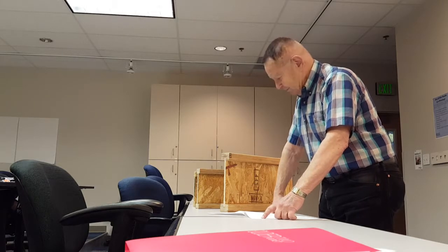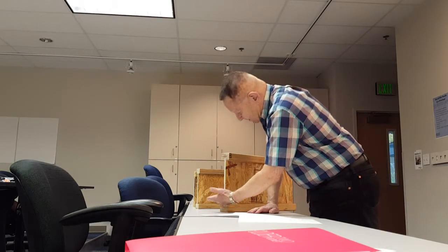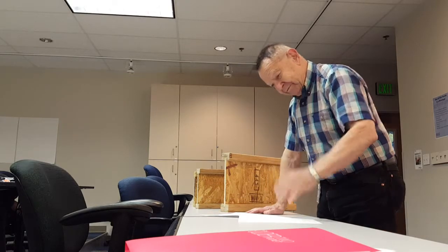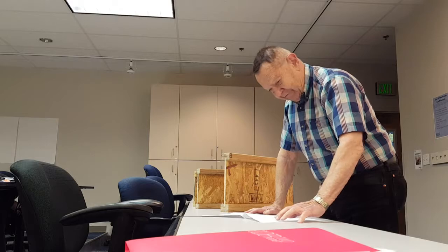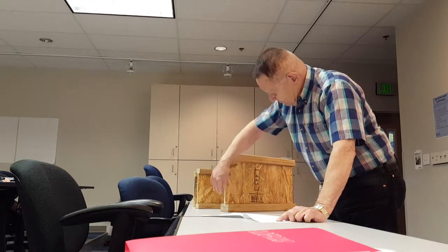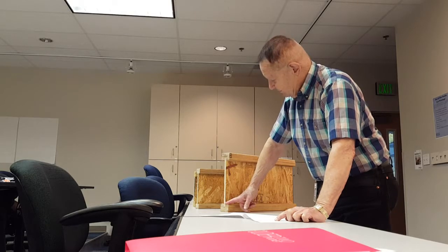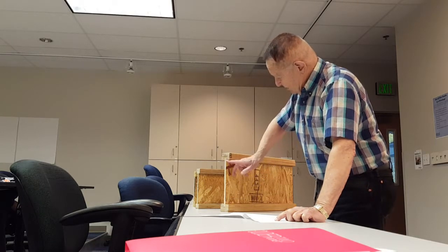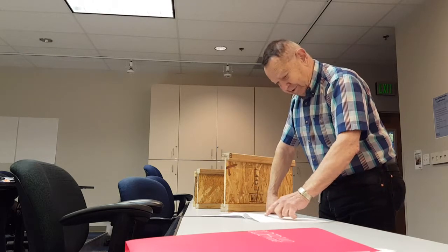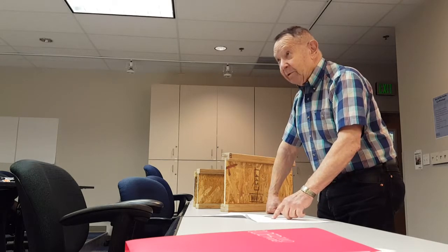So call that moment of inertia 1, which is from an axis down here at the tabletop, really just for this bottom rectangle. Then for the oriented strand board, from here up to there, you have your density and your width, and then from the bottom, which isn't 0, it's y equals 3/2, up to the base of the top rail, which is the 8. And so you work that out, and you see that's I2, and that's a lot bigger number